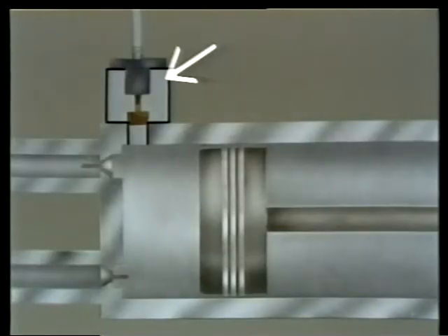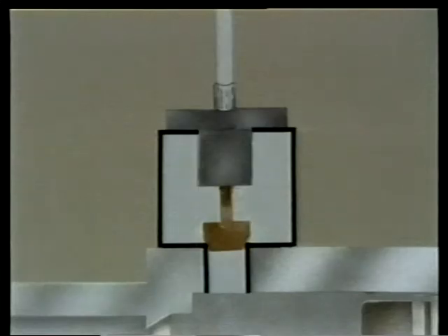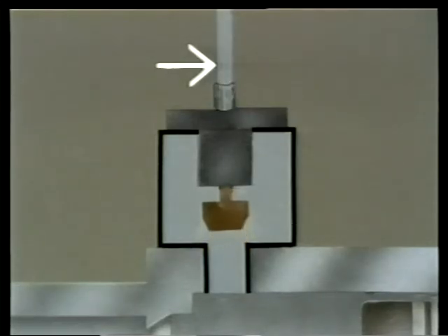When a reciprocating compressor is operating with the inlet valve unloaded, you've effectively stopped the flow. Sometimes, though, it's not necessary to completely shut down the flow of air into the receiver. You might want to just slow it down instead. When that's the case, you can use a reciprocating compressor with clearance pockets. This chamber is the clearance pocket. It's an airspace that's connected to the cylinder, but it's isolated by this normally closed valve. The valve's operated by an air line that goes to the receiver.